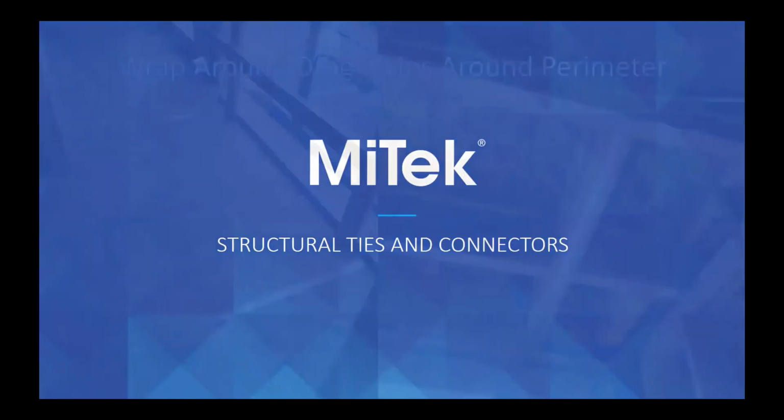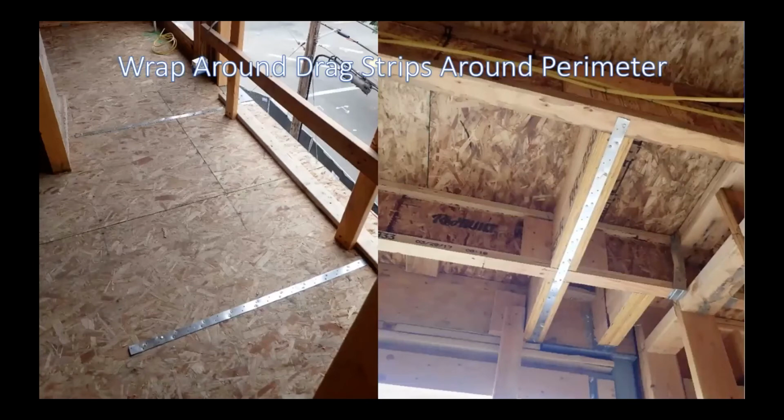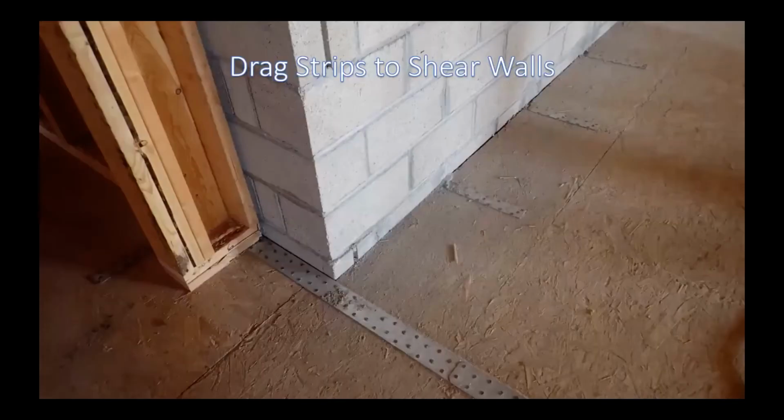There's a lot of connections and ties being used. We see a lot of drag strips being used, whether wrapped around the perimeter edges, as you see from the top, down below into the blocking, to tie the perimeter building back into the primary structure. They do that in a lot of cases right around the building. A lot of them are also tied back to shear walls to provide a lot of continuity, depending on how the bracing system in this building is done.